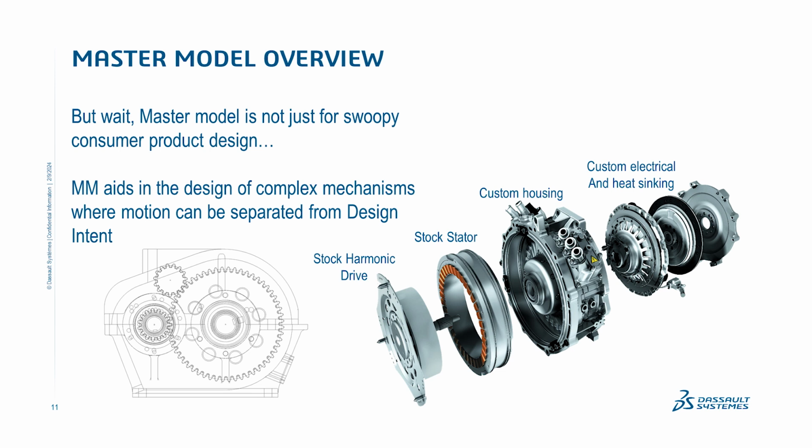So having that all in one part file to design is really valuable and very efficient, I might add, because you're just working with a single master part file, and you don't have to be jumping around between different parts if you were to do it in an assembly and make it in context of an assembly. It's very convenient to have it in one part.